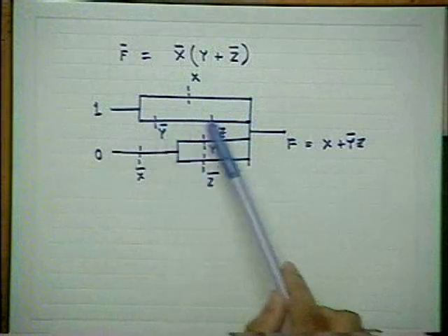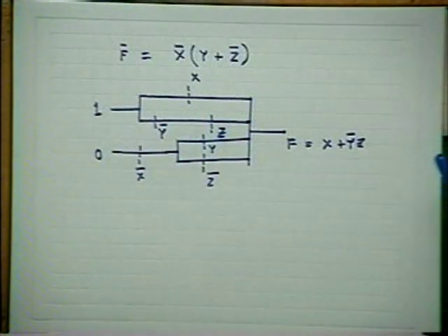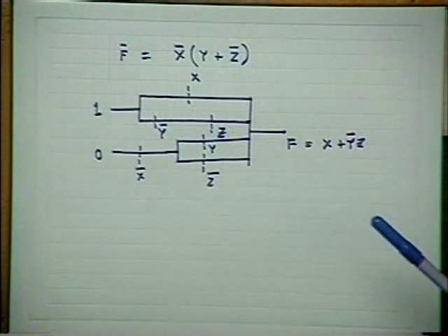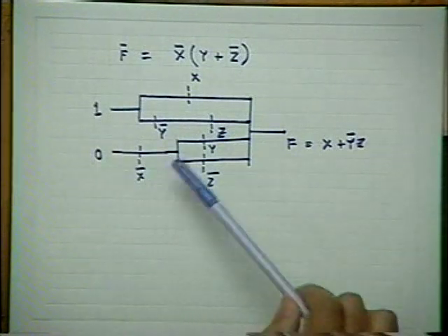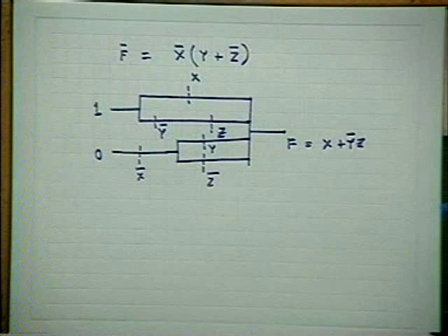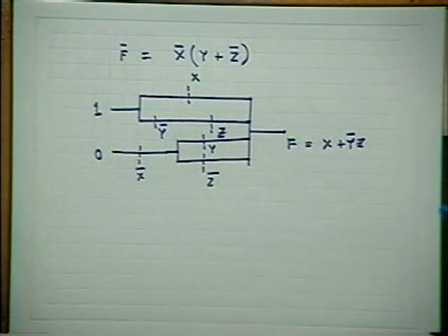And how many have I used? 3. And one can see that you will find here, how many transistors have I used? 6 transistors. So one can see that ultimately there is not much benefit to be derived if you do this, so far as packing density is concerned. But one great advantage of this is, in this case, you don't have to maintain the ratios, because these are all independent switches. The ratioed design is not important here. You want to just transfer ones and zeros.